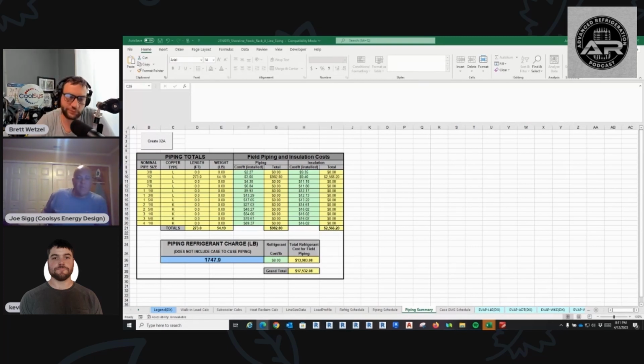And one thing you'll probably never see in a CO2 system is horizontal receivers or horizontal flash tanks. They're all vertical because they're trying to maintain a solid column of liquid out to the fixtures and surface area. If the receiver or flash tank is standing up, you've got a smaller surface area to push on than you would with a horizontal.